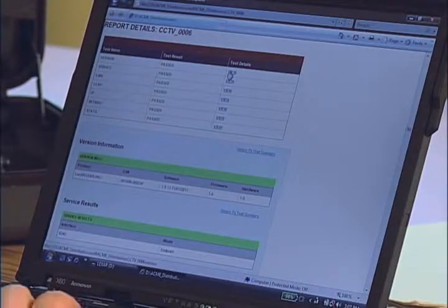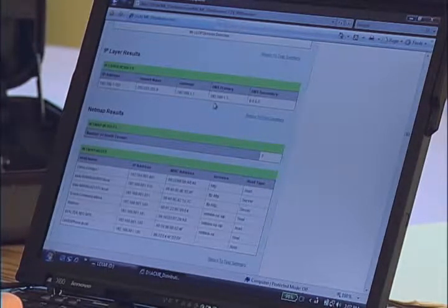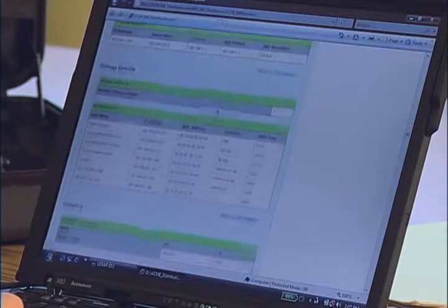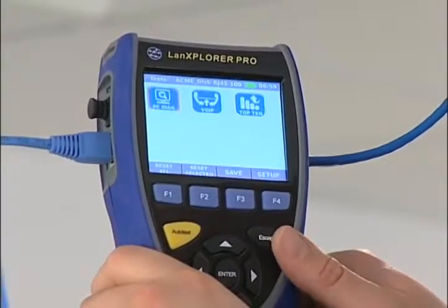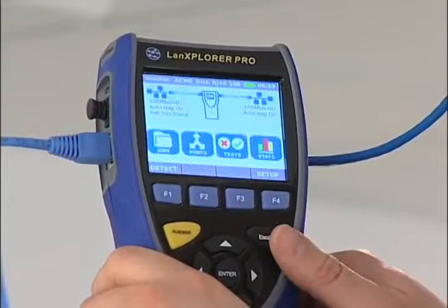This test lets you determine if excessively long cable runs are causing a voltage drop, which may prevent continuous operation of a PoE device. Pass-fail limits can also be set to include PoE load testing as part of your selective auto test suite. The Lan Explorer Pro model, with its 2 copper ports, can perform inline PoE testing in addition to load testing.